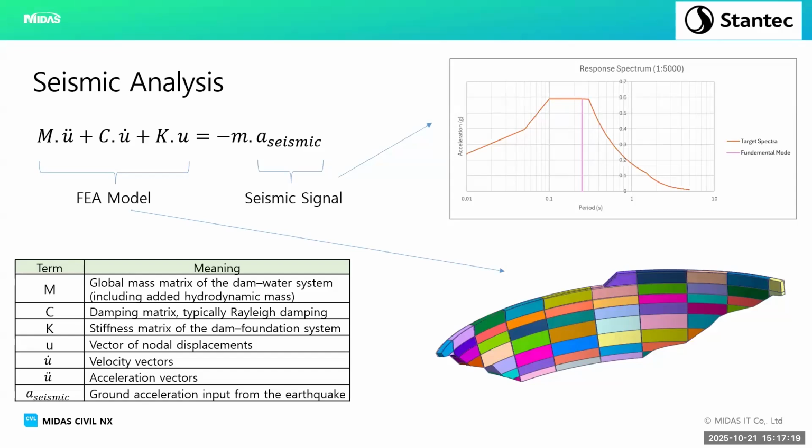I know there are rules of thumb: if you look at an operational basis earthquake, you use 5%. If you look at a safety evaluation earthquake, you use 7%. But it can be debated, because Anil Chopra has shown from testing on site that it can be as low as 2 to 3%. Again, that's prior to any significant damage. So that's a very important factor that can't really be pinned down straight away. And the rest is easy to define. All of us define the FEA model on a day-to-day basis, whether it be a bridge or pushover, anything like that.